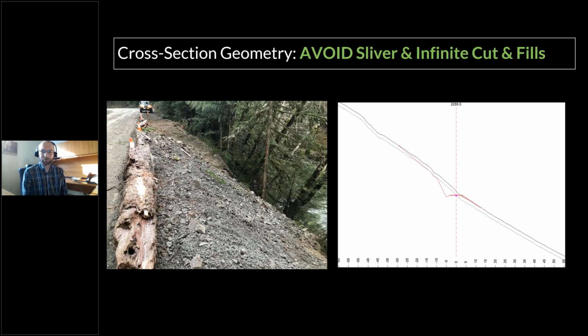But if you're thinking of going that route, you really do need to ask yourself, does it make sense to absorb those costs? And if you're not willing to, just remember that poorly built cut and fill slopes may fail, which is a safety concern, but it's also an environmental concern, which is why everyone's here. And that could be a catastrophic failure causing a landslide going down into a creek, or it could just be raveling material filling in your ditch. Of course, it's probably not going to happen where you expect it. You're no longer controlling where that water is going, and maybe you concentrate flows to somewhere that hasn't seen much flow before, which causes erosion, which feeds into sedimenting a fish creek.